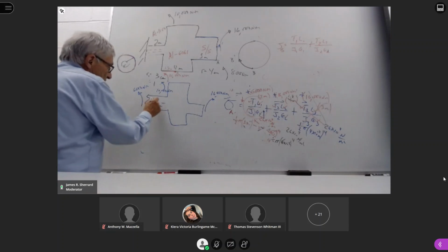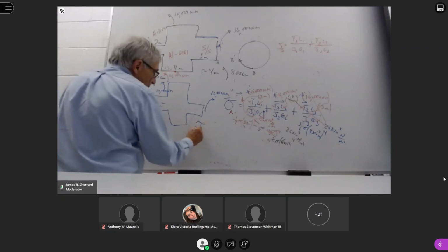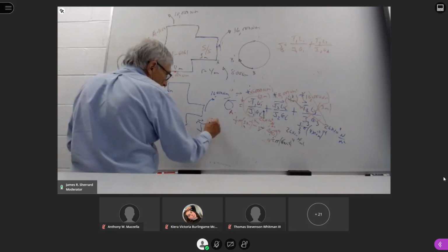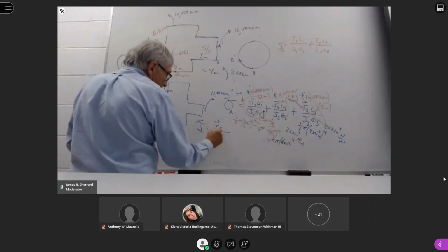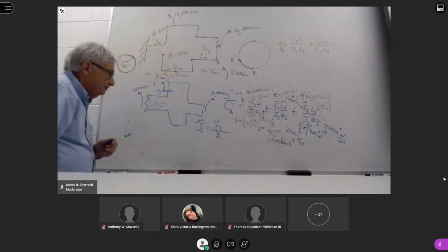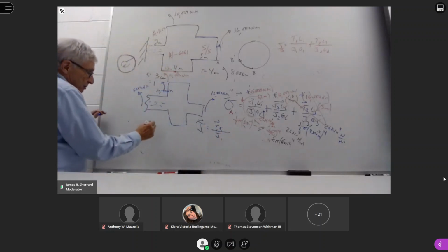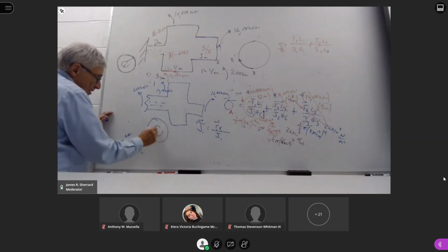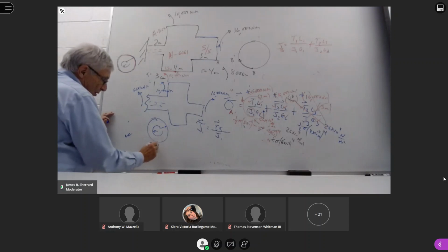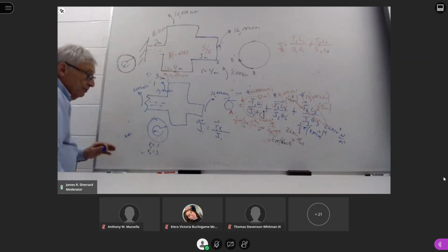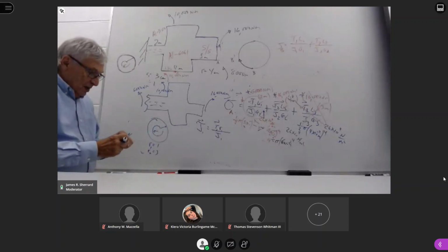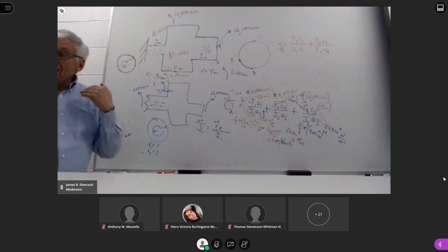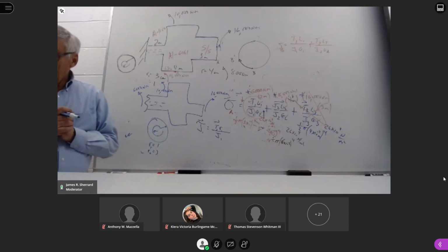Then when I go to find out the safety for region 1, we know that the shear stress there is equal to the applied torque times the maximum radius over J. When we look at this section, again, we have an inner radius of 1, outer radius of 3. So we know if it's failed, it's going to fail on the outside. This calculation is exactly the same.